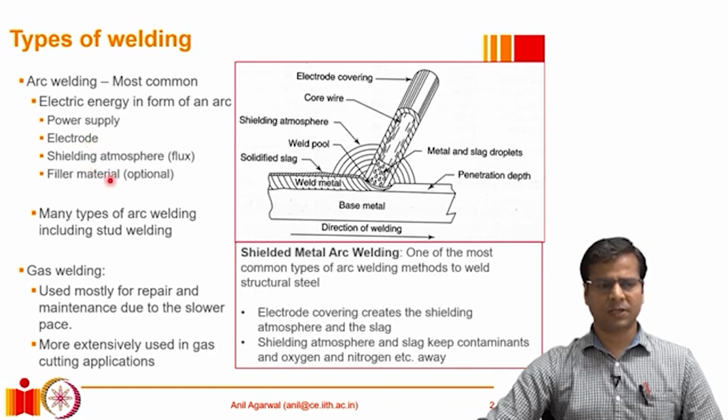One of the parent materials acts as an electrode, and then they fuse together without any additional filler material, such as when the shear studs are welded to the flanges of floor beams. They are often done through an arc welding process, but there is no filler material utilized.